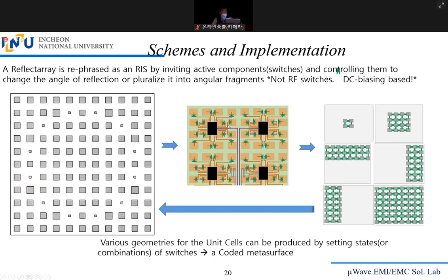Then you can choose on, off for each of these unit cells. So say, for example, 1, 2, 3, 4, these are on. The rest of the checkerboard from the subarray are off. You can see this. And this will be the smallest one, for instance. And you want to increase the size of the metallized part. Yeah, these switches are called DC switches, not RF switches.